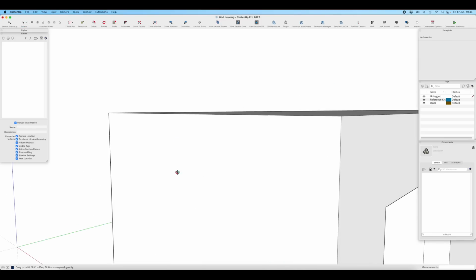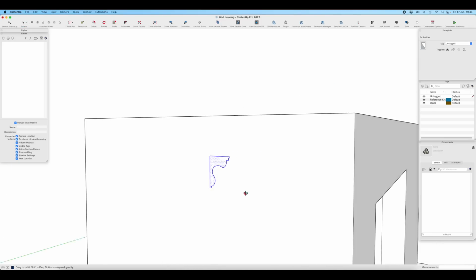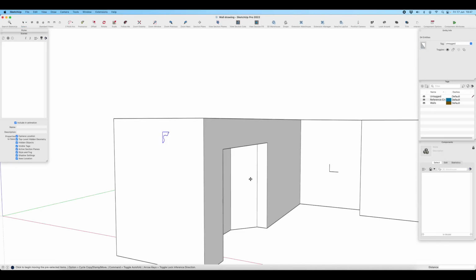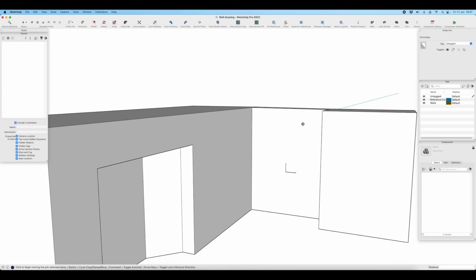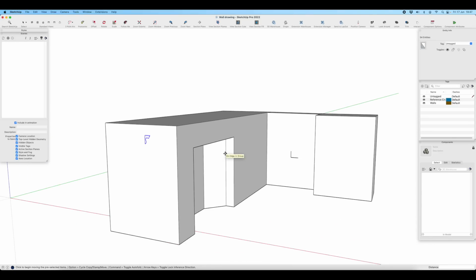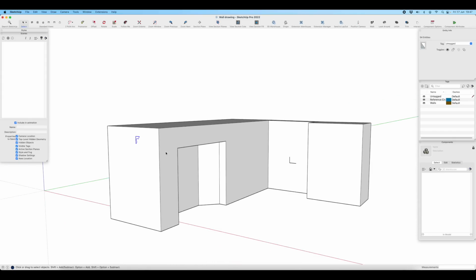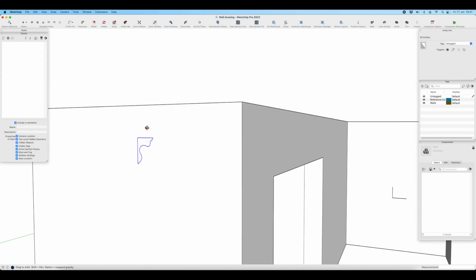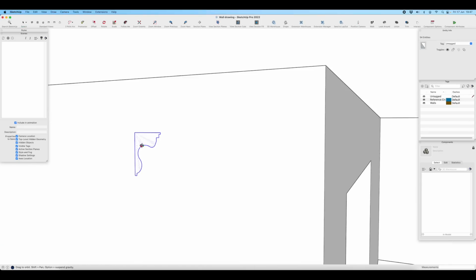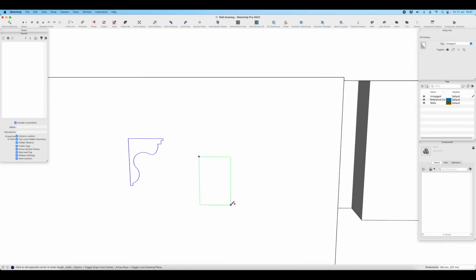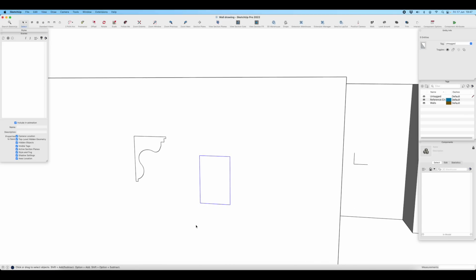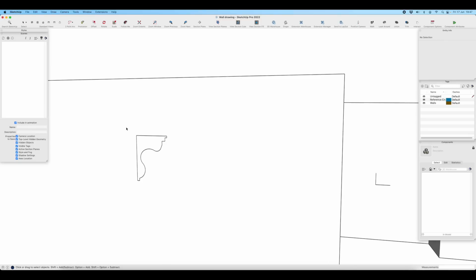Now here's one that I've pre-drawn before and is the right size. I actually drew this with everything else and filmed all of this process of drawing this out, but I forgot to turn the microphone on, so it kind of ruined that video. So this is the second time I'm drawing this out for you lot. So there's my cornice section, just drawn. If you draw a square and then draw your profile in that 2D square, make sure it doesn't come out of the model on the wrong axis. You can't go far wrong.